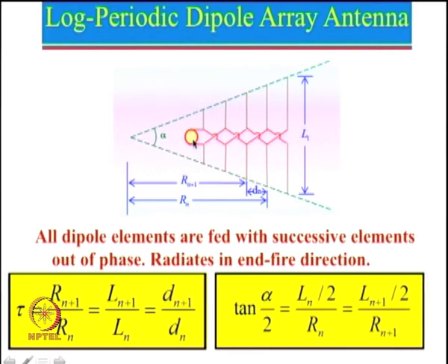Whereas, if we feed from this side, there are chances that at higher frequency, where this is supposed to be resonant, higher order modes may get excited. So part of the power will be radiated through here and lesser power will be there. So, in general you should keep a point that always feed from the lower dipole dimension only and not from the higher dipole dimension.